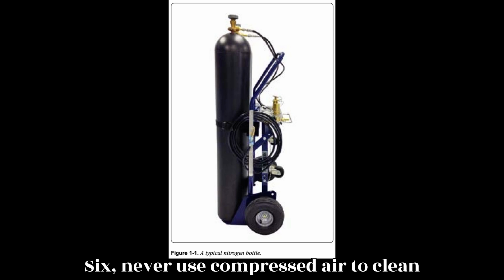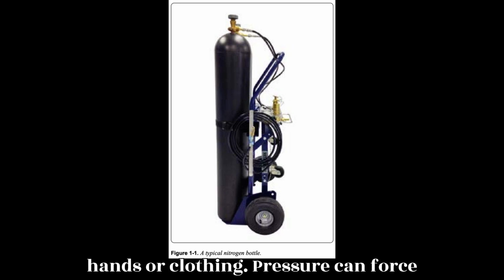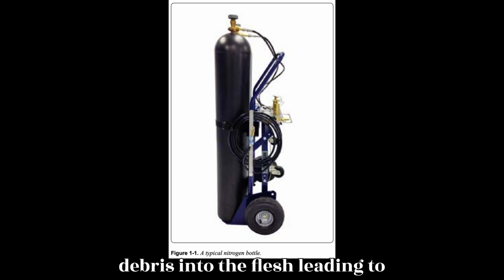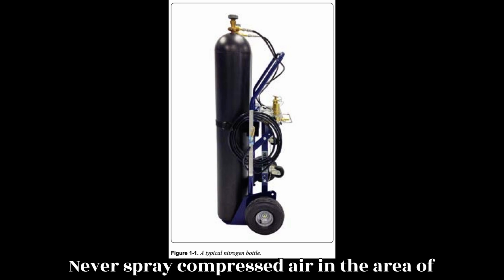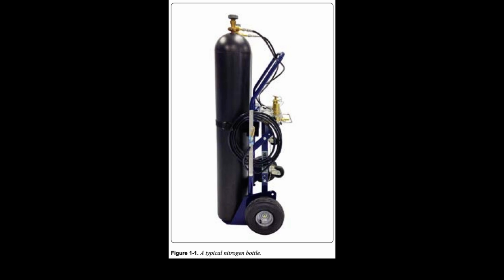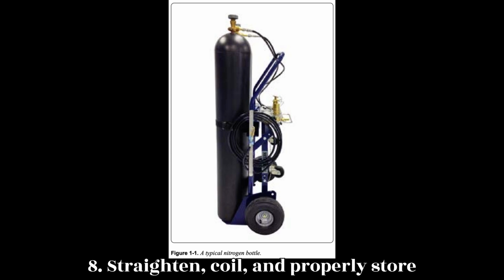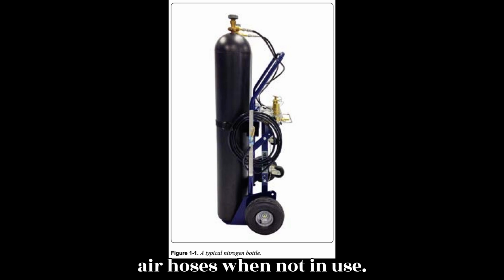6. Never use compressed air to clean hands or clothing. Pressure can force debris into the flesh, leading to infection. 7. Never spray compressed air in the area of other personnel. 8. Straighten, coil, and properly store air hoses when not in use.